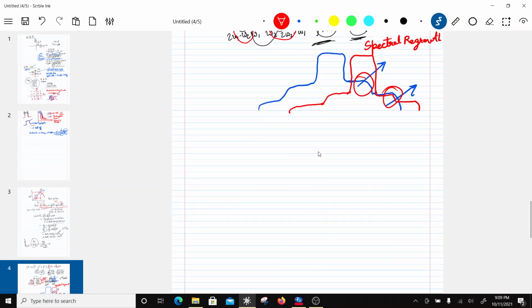And what would that mean? That would mean the following. If I have the linear component, let's say this is growing like this, and as soon as I go into non-linearity, which is let's say over here, the IM3 components are going to grow faster. So basically this slope is 3 times this linear slope.